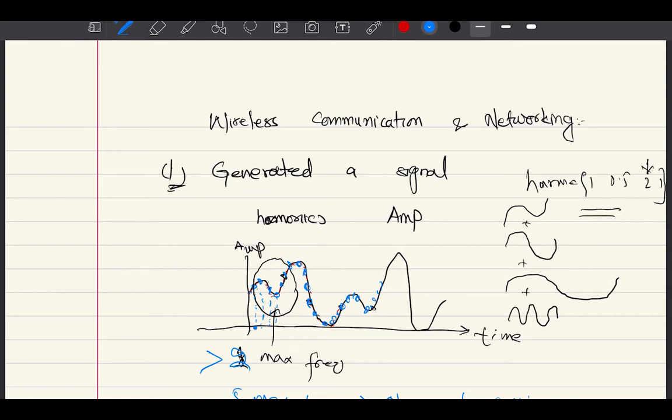Again, we skipped three other signal points, and then chose the fourth. So we were choosing 1/4 of the points, not every point. This is not the exact solution, just to demonstrate how it works. You should sample in such a way that it obeys the Nyquist criteria.